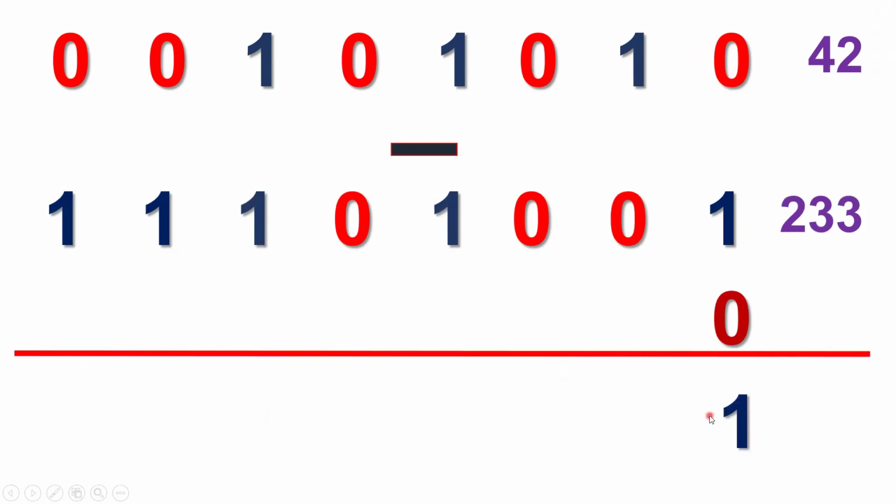So here is the difference. Now, you see that the borrow that you borrowed from the next bit, you put the borrow here. Therefore, you can read it as 1 minus 1 now. So it is now 1 minus 0 is equal to 1, and 1 minus 1, the difference is 0. And again, at this bit position, to do this subtraction, you did not borrow anything.